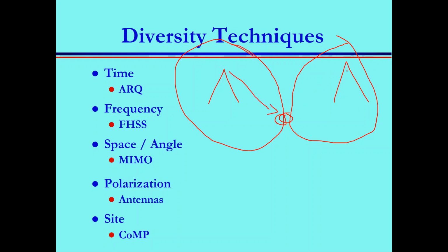So the base stations agree among each other: let's share the data of this user among us and send it jointly. So this receiver receives his signal from both base stations jointly. This has different fading, different performance, different interference, and that one has different interference, different fading. So if this was bad, this might be good. Your probability of making error reduces.